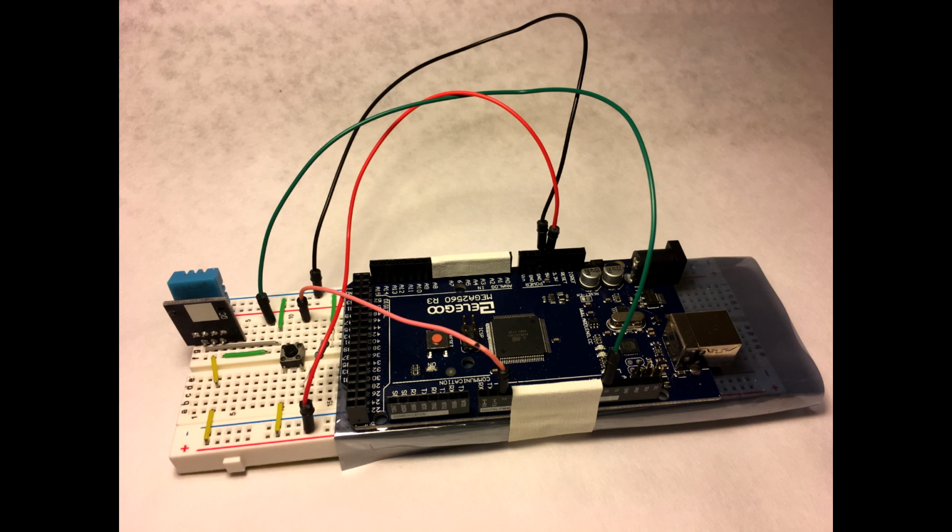This project will wait for temperature to stabilize and then record temperature readings every 10 seconds for 5 minutes. It then waits for a button press and records temperature at the same interval for another 5 minutes. It uses a round robin with interrupts design to accomplish this.